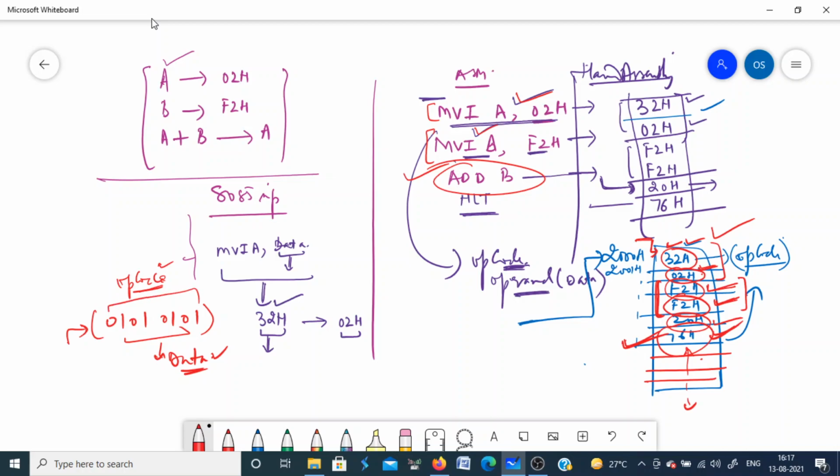Now if that instruction is a 1 byte instruction, it is completed in a single shot. If that instruction is a 2 byte instruction, it means you need one more byte to supply, which basically supplies the data for the instruction. That will be in the next memory location, and so on. Similarly, we have some instructions which are 3 bytes also. The first byte is the opcode, and mostly the next 2 bytes carry the address of some memory location.